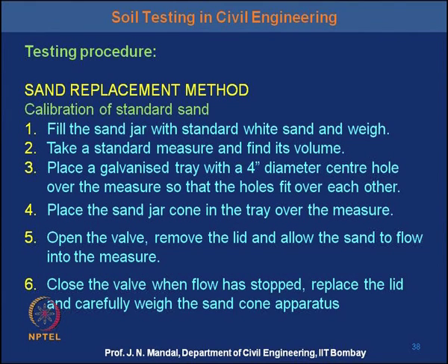Then open the valve, remove the lid and allow the sand to flow into the measure. Now, close the valve when the flow has stopped. Replace the lid and carefully weigh the sand cone apparatus. So, this is the way that one has to perform the test.